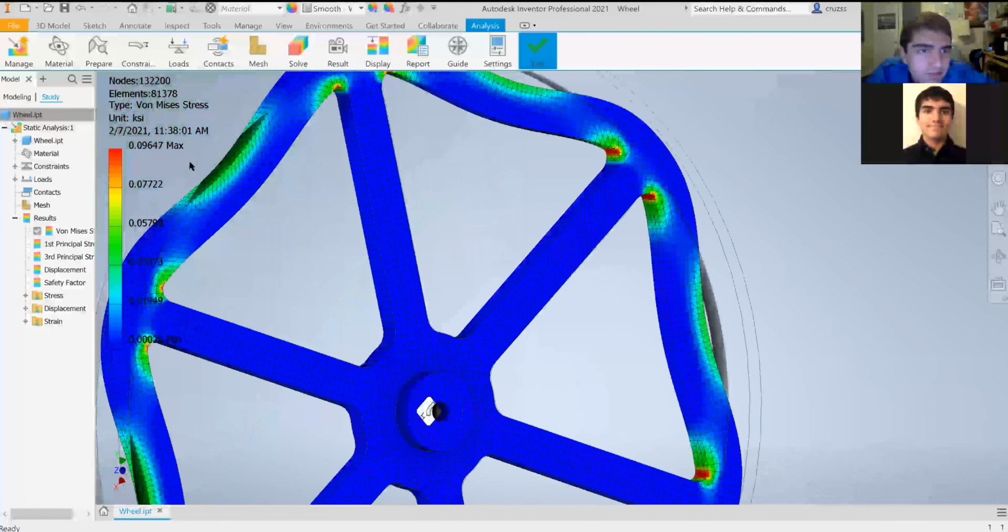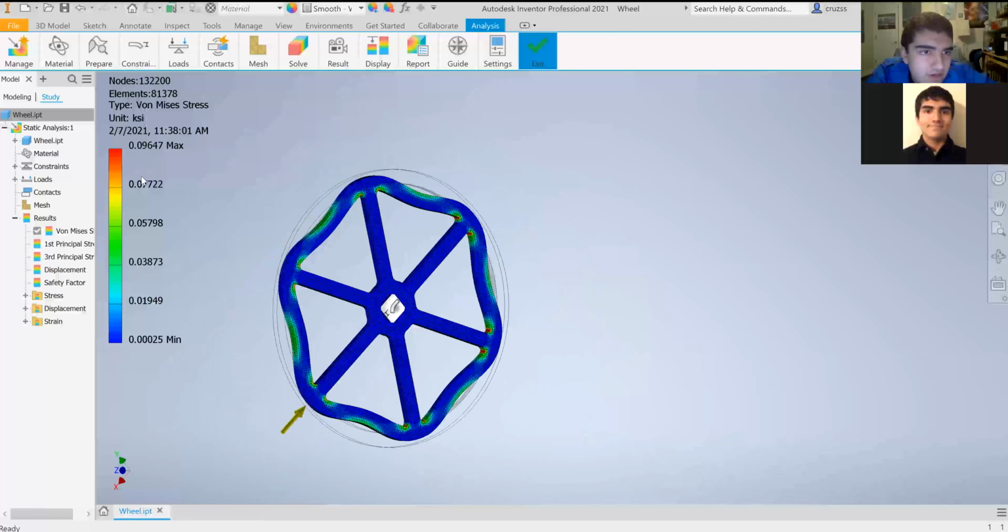And as you can see, this is going to give us the von Mises stress in the top left corner. And so it's going to number that off from a certain value minimum to a certain value maximum. Generally speaking, different items have different stress tolerances, but the von Mises stress on here is relatively low, about 0.1. So chances are you're not going to see an immense amount of permanent deformation on this material, if any.